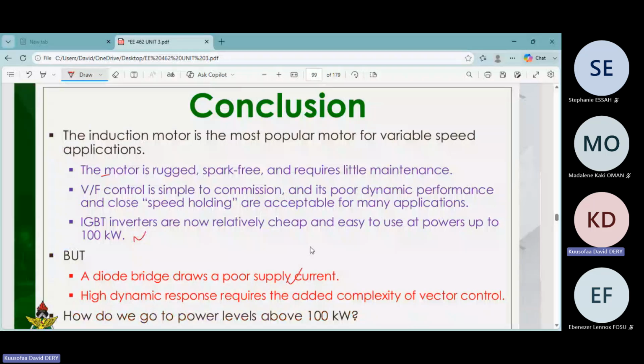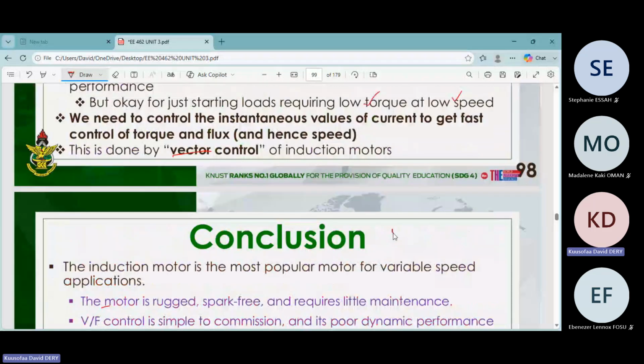We want the motor to operate at the rated values, so flux should be rated. In order to maintain the rated flux, we have to ensure that IM, the magnetizing current, is constant. The magnitude of IM is omega VM over omega E LM, and we saw that this is a constant. Omega E is the speed that you can vary. When you change omega E, VM will also change by the same proportion. That is why we need to vary the voltage.